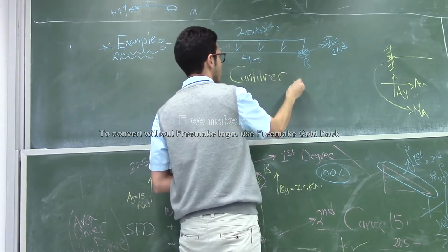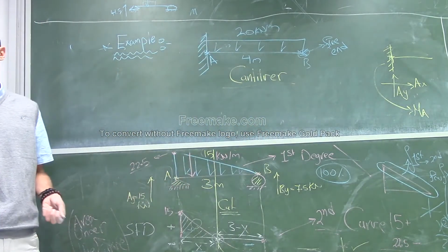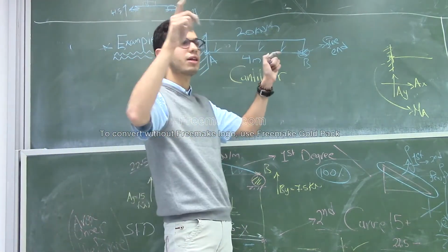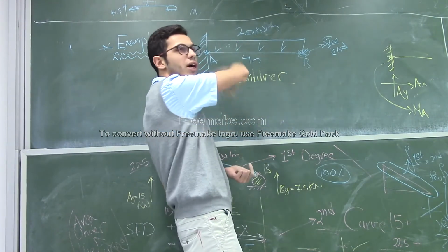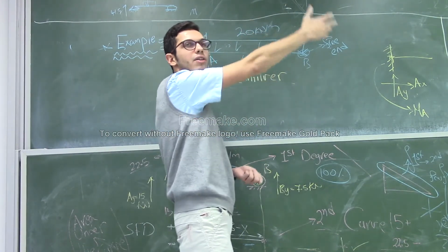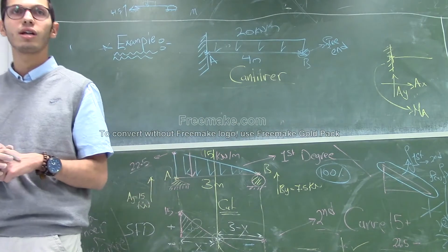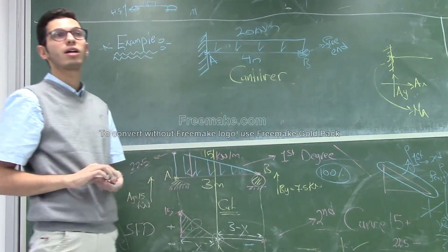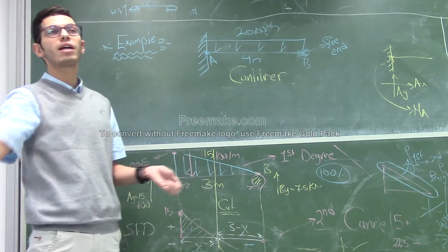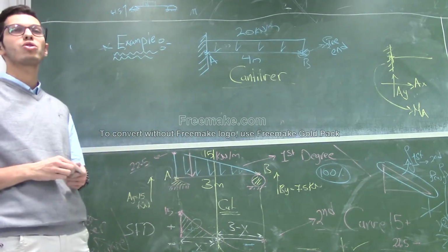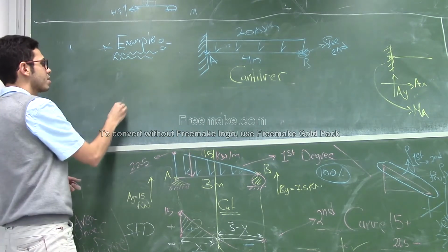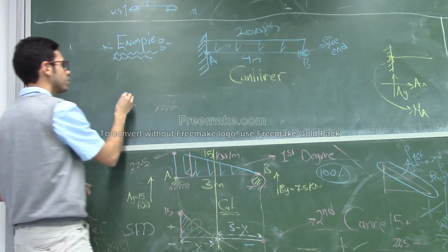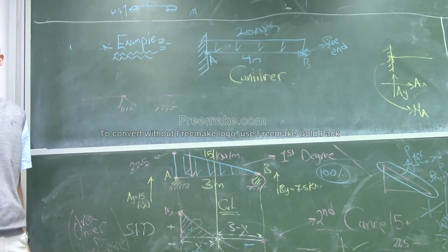Cantilever, okay? So in the future, if an engineer says cantilever, you should always remember this. Cantilever means that you have a fixed support at one end and the other end is a free end. If he says simply supported beam, that means this shape. If he says overhanging beam, there are many names that you should know. Overhanging beam is like this. Okay, it's an overhanging beam.